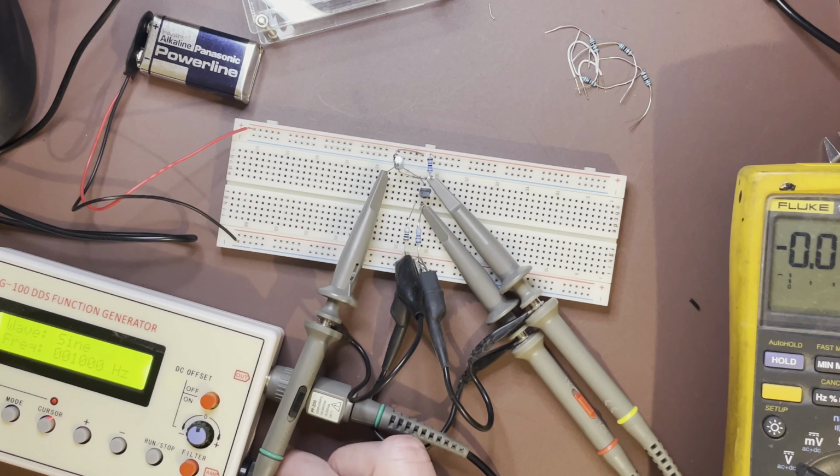Now the next thing I mentioned earlier is that the AC gain can be much higher. The DC gain needs setting to work out the bias values, and you can't really go very high on that because of the resistor value ratios and the possible swings; the emitter voltage starts to get too low to be stable and guaranteed to work.